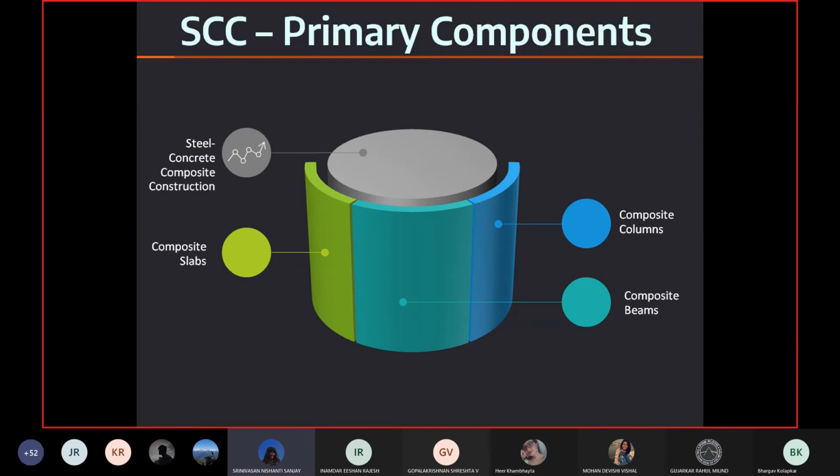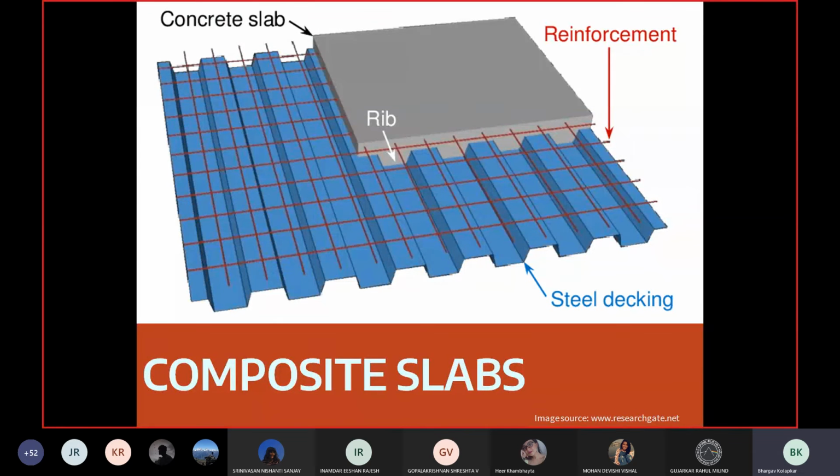Would grillage foundation count? Yes, yes, very good answer. So grillage foundation, we looked at that, wherein there's a set of steel beams orthogonal to each other in different layers, and everything is covered in concrete. That is a form of a composite foundation, but it is very, very rare, and therefore I'm not including it here. And we've already looked at it.